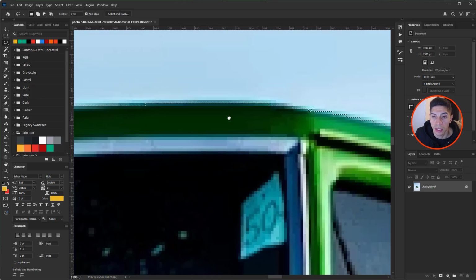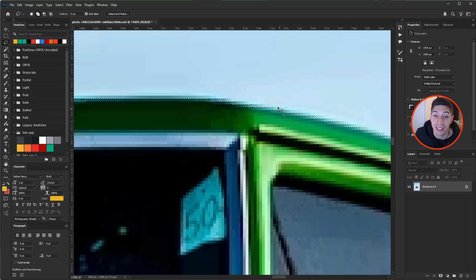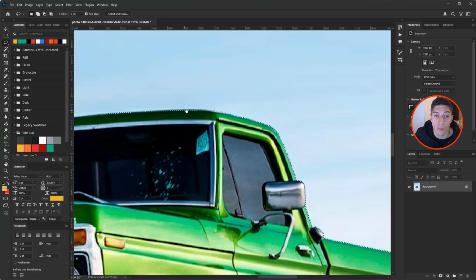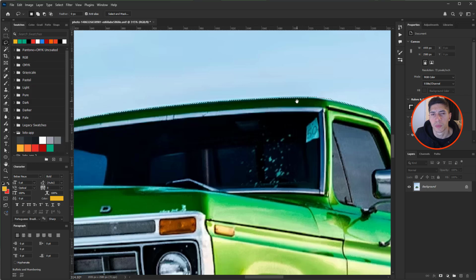And I want to just select this little bit of portion over here and accidentally I select more than I wanted. Remember what I told you? Hold Alt and then you click and drag and now you're going to drag outside of the selection and you release the button and it's going to be selected over there. Okay? Actually unselected. That's how you want to do. Okay, that's pretty simple. That's probably one of the easiest ways to add and remove things from your selection.